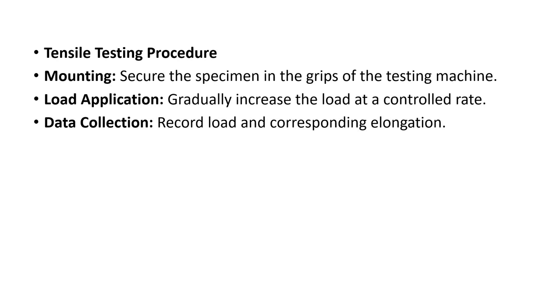Second one is the load application. Gradually increase the load at a controlled rate. Load is increased gradually. Suddenly load is not applied. Load is increased gradually, that is step by step, up to the fracture of the material. Third one is the data collection. Record data and corresponding elongation. We have to record the data of load, then its tensile strength, and also corresponding elongation, that is strain. How much that component is elongated.